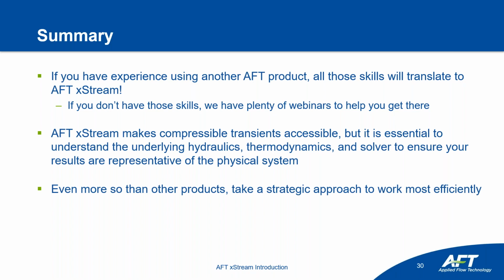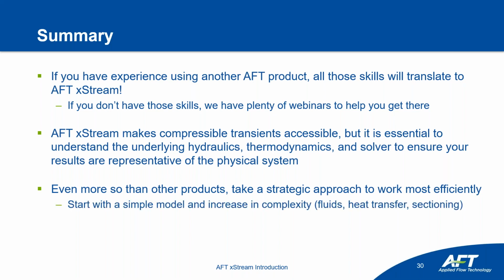Even more so because it's going to be more calculation intensive, recalculating fluid properties depending on how we're sectioning the model and doing those interpolation calculations. It's important to take a strategic approach to work efficiently. So start with a simple model and then increase your complexity. Maybe you add more fluid specifications, you add heat transfer, you add additional sections. And then also, of course, ensure that you have enough sections for an accurate representation of the physical system.